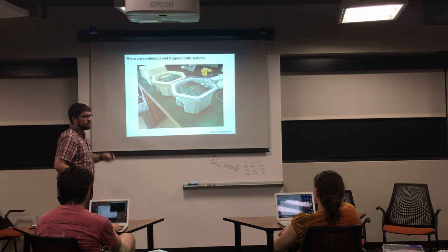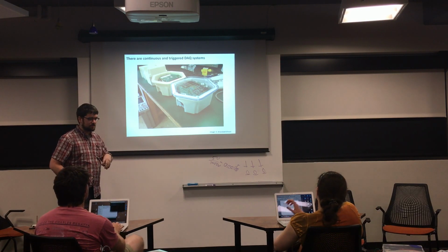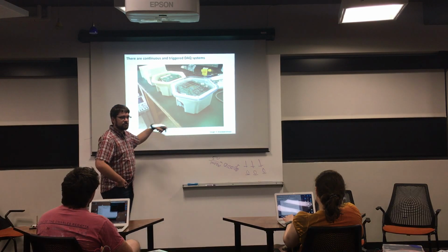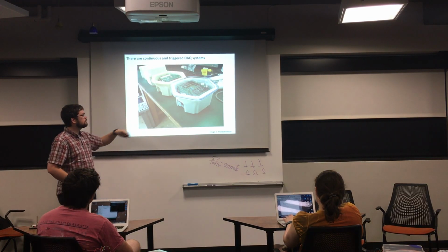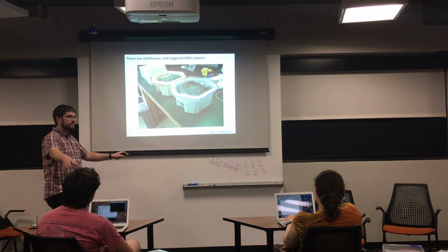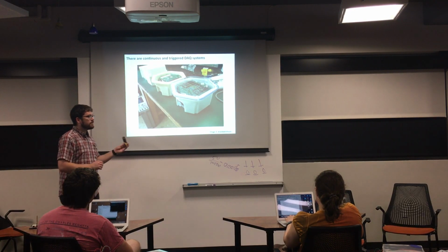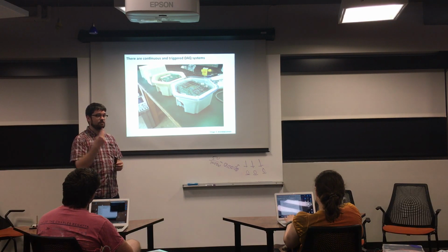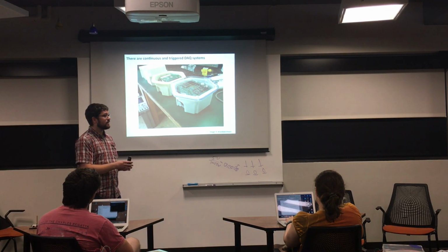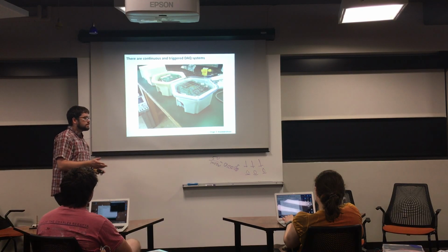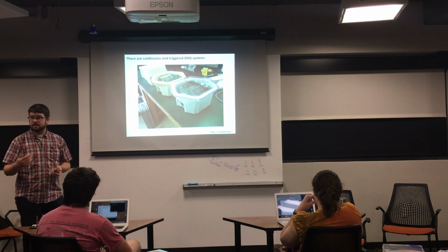So there are two different types of analog to digital converter systems. These are the GeoPebbles that Sridhar and folks in the ICE group have been working on. These are 3-component seismometers that they lay out, and they form a mesh network and send the data back. And they're actually a really good example of one device that has both types of systems in it. In fact, it's the same hardware, it's just how you have it set up. So the two types are a continuous system and a triggered system.